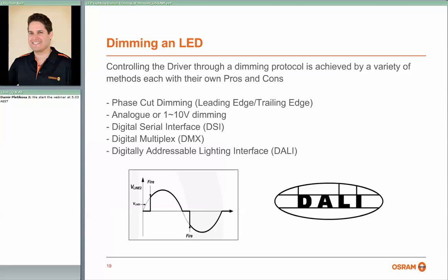And then we've got DALI, which is digital addressable lighting interface, which is quite common for commercial installations of office buildings and things like that, where ballasts and drivers and so on and fittings themselves can individually be addressed and controlled via a control BMS system.